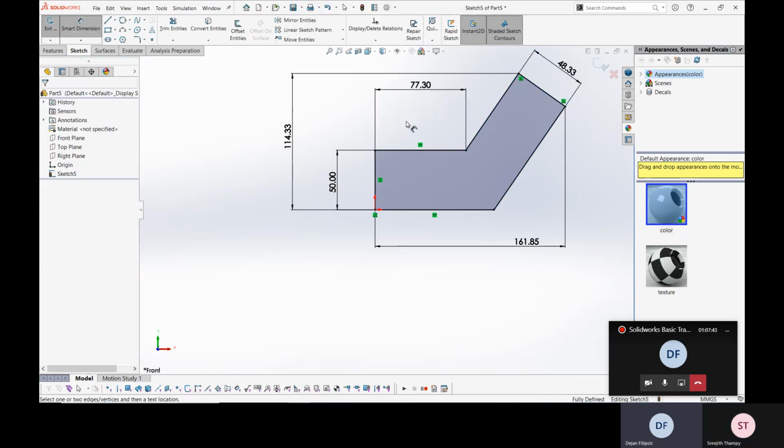That's as rigid as you want, right? Because in some cases, when you do modeling, you maybe don't want to put all the dimensions on because you don't want to constrain everything because it's not important to you. For example, you have a certain type of shape and you know what you've done is good enough. You don't have to put another 5 dimensions on because it doesn't mean anything to you. So you can kind of do a 3D and progress with that. Nothing will change that shape later on because as soon as you go out of the sketch, you lock it and that's it. So all the changes and all the features you introduce after, they can't change what you've done before.